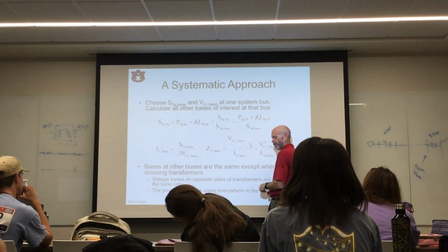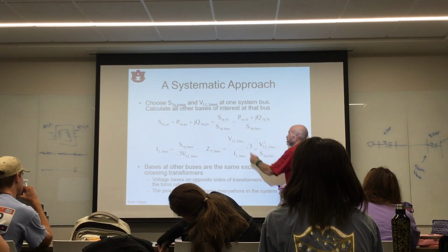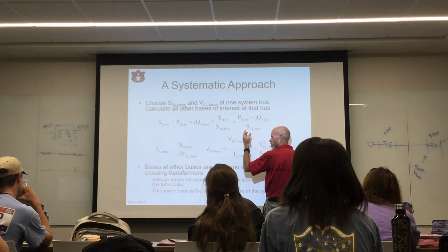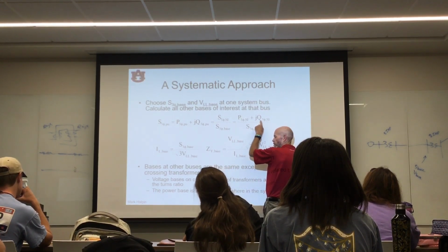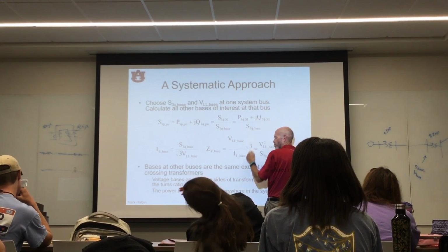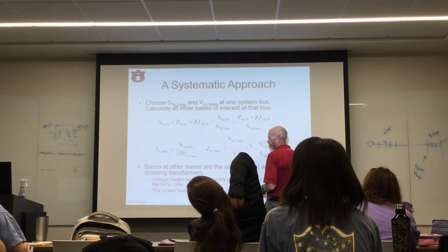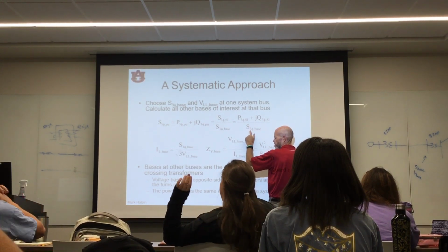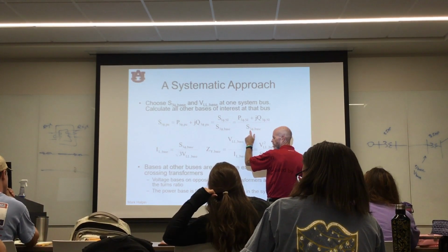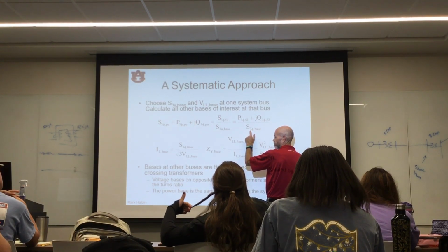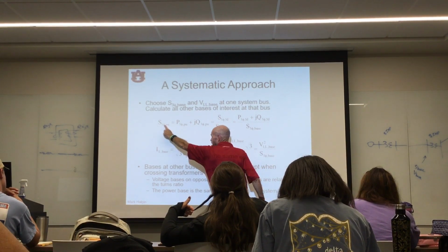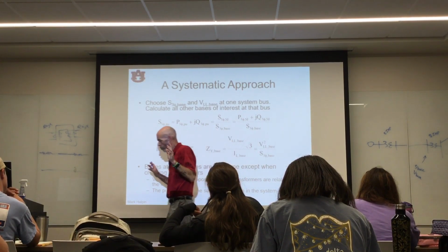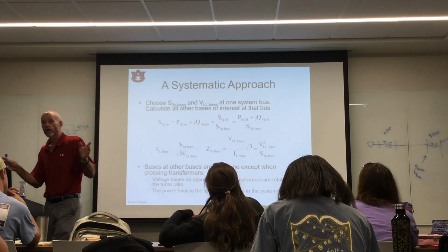Watts over VA, what's that going to be? This is a power, and this is a power. Power divided by power is unitless. The point here is that the apparent power base, S base, is the same for complex power, or real power, or reactive power. We only have one power base, and it applies to every power quantity.